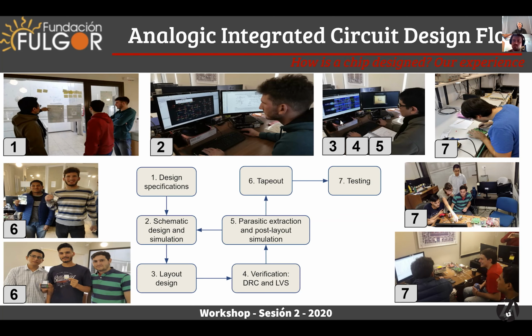Here we don't have any standard cells, as you say, so we draw the transistors one by one, not exactly one by one, because in Magic you can draw one transistor and say, well, this transistor will have this length, this width, and it will be formed by, I don't know, maybe 10 transistors or more, and you have the whole package drawn at once.